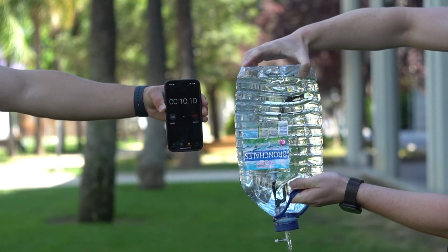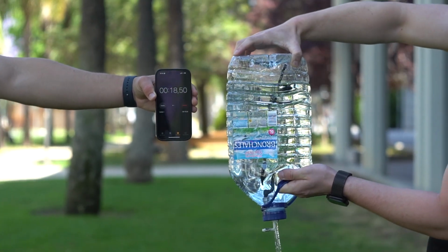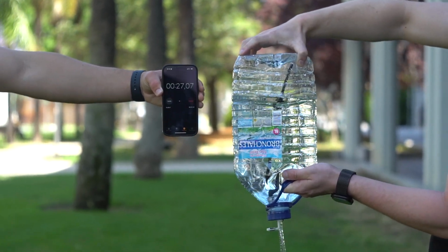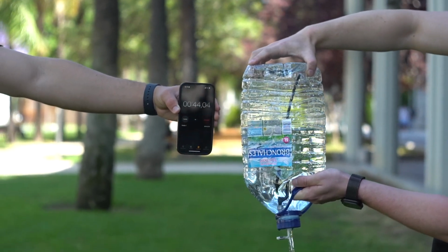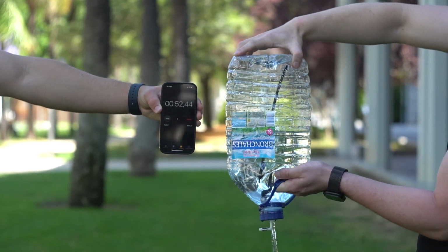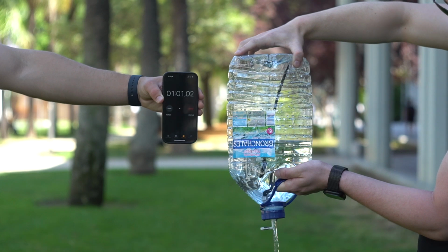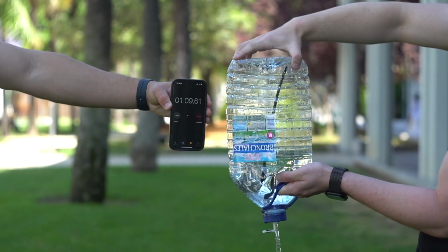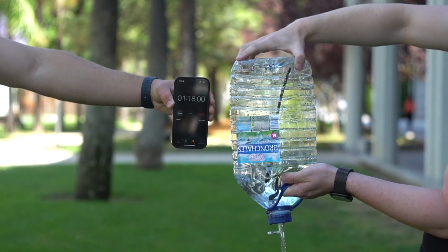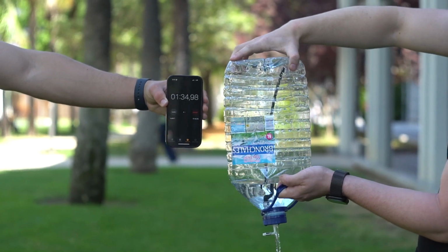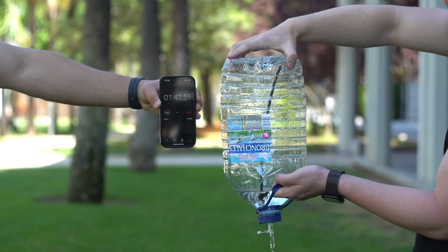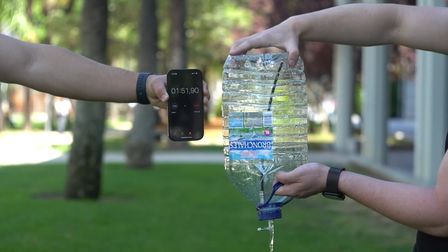We conducted 3 drainage tests. The first clip shows the drainage time using the initial nozzle, which features a 3 mm diameter air intake. This experiment confirmed that sufficient air was entering the bottle through the tube, as the bottle did not compress during the process. The total drainage time with this fitting was 1 minute and 53 seconds, which, when compared to the theoretical time of 60.73 seconds, resulted in an efficiency of 53.74%.